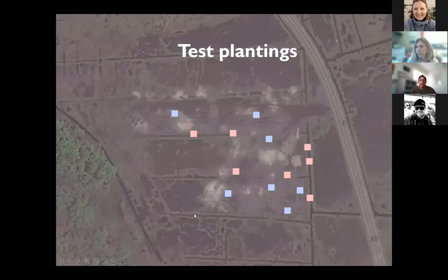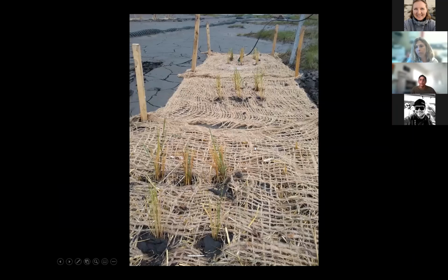In addition to that, to add value and learning from this experience, I did some test plantings and some little plots with different treatments, all geared toward anticipating dry conditions at the site because we're raising the elevation. We heard in the last session of this webinar series the concerns about material drying out and becoming acidic, so that's something I had a real eye on. We were measuring pH and moisture at these plots, with treatments designed to retain moisture.